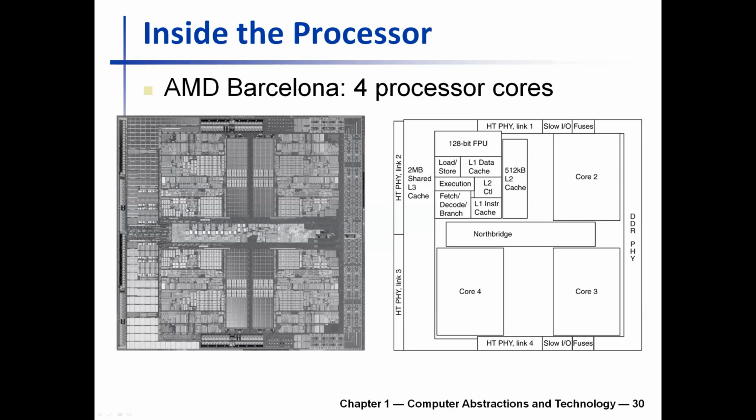So instruction, that is the 1s and 0s instructions stored in the memory, bringing the correct one into the CPU and making sense of those 1s and 0s. That is decoding. Making some sense of those 1s and 0s is done by the logic circuit here. And the rest of these things are more memory related. So this is a level 1 data cache.